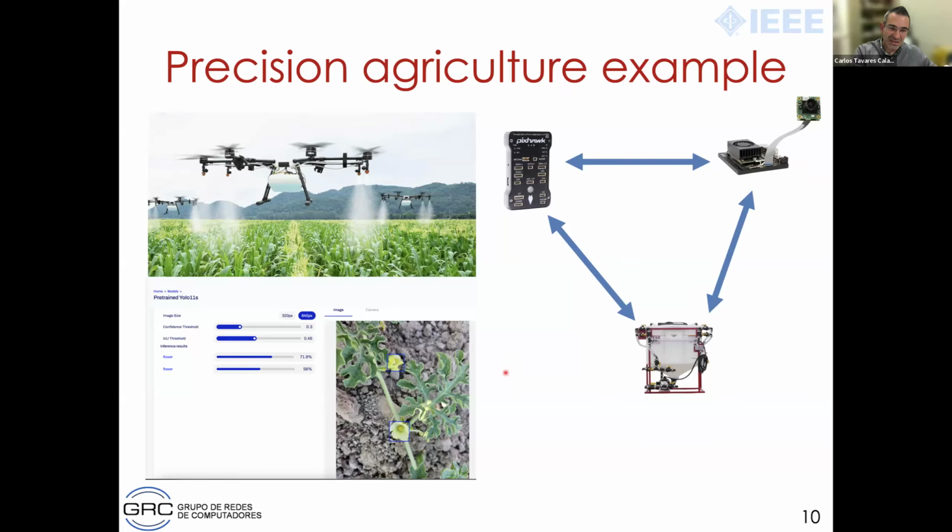So what we need is something that resembles more the communications in VANETs, where in 802.11p you have this outside-of-the-basic-service-set paradigm of communication. So you don't want the drones to be previously linked to each other from a communications perspective. You want to allow new nodes to just join the network at any moment. So we should have a technology that enables this type of interaction between drones. That is from the physical and MAC layer perspective.